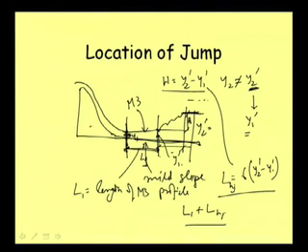So we need to do something so that we can contain the hydraulic jump just at the foot of the spillway, or just on the downstream of the spillway, so that we can avoid taking protective measures for a very long distance, and we can contain the jump here.